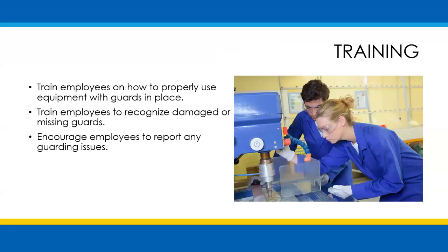Train employees on how to properly use equipment with guards in place. Train employees to recognize damaged or missing guards. Encourage employees to report any guarding issues and develop an effective reporting system that promptly responds to these reports.